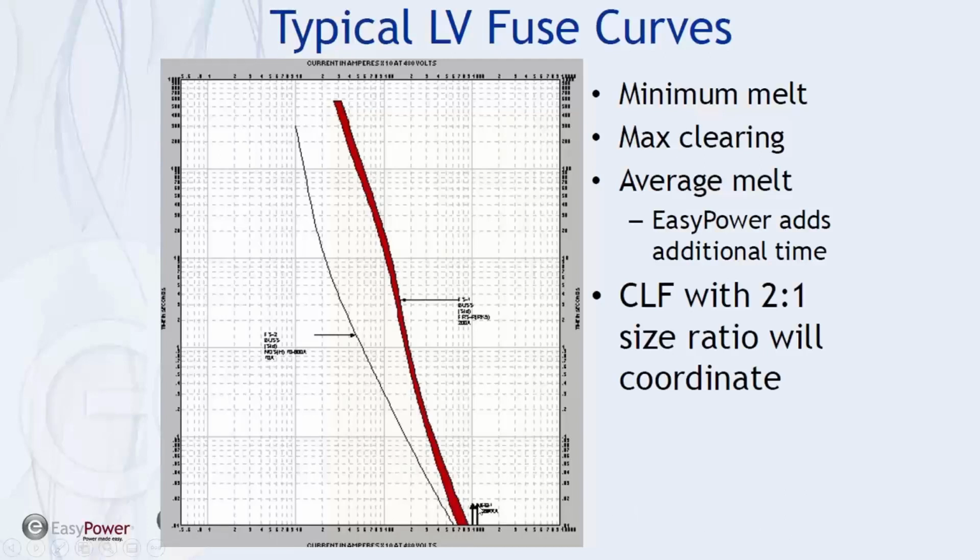And so when we see fault current that's above the plot line of the TCC plot, the inference is that it's going to trip the fuse sometime before the 0.01 timeline. If that information is provided to EasyPower, then we will plot the curve below the 0.01, but if it's not provided, the curve stops at that point.